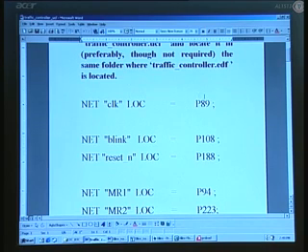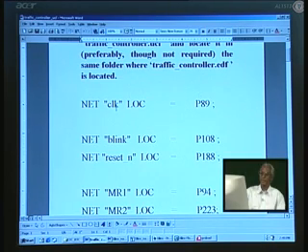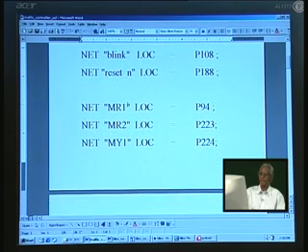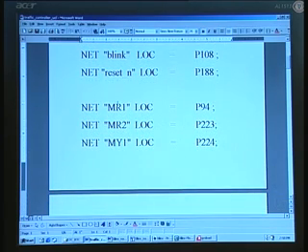It is to signal to the tool that you want to use this clock signal as pin 89, because we are now concerned with the hardware connection on the FPGA. And this user constraint file abbreviated as .ucf is precisely to tell the tool that such and such pin is to be taken as a particular signal. For example, 3 input signals are clock, blink and reset_n, which we have already seen quite a number of times, and we had 16 lamps, say LEDs, and these are all the nomenclature we adopted for main.